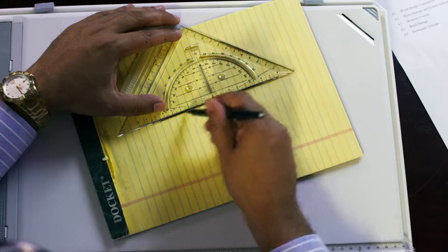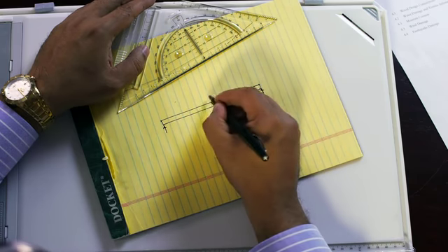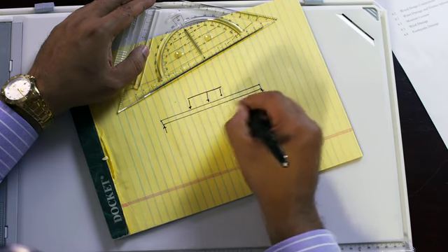What is a beam? A horizontal member which carries load vertically. Definition of a beam. And how does it transmit that load? It transmits that load to the columns or shear walls in the form of bending, which means it's going to deflect like this. And when it bends, the maximum bending stress is occurring at the center span. That's where your highest deflection is. So this is your maximum moment, your maximum bending stress.